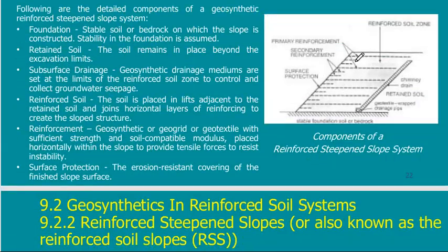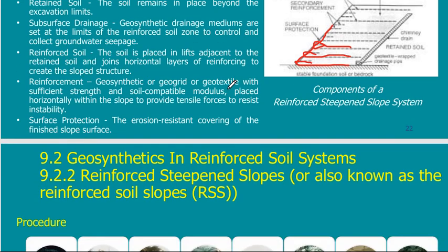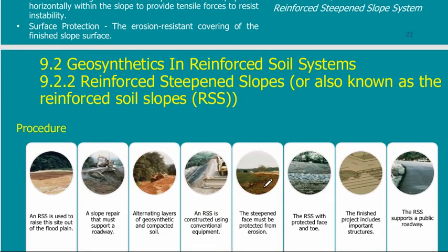So this is how we use it for reinforcing the slopes. I may use a wrapping system similar to the one I proposed before. We can put just the material here and wrap it like this, another one here and wrap it like this, and so on, each one, and put the soil material in between. I end up, instead of having a wall, with a slope going like this, and this slope would be very stable, and I can guarantee its lifetime.